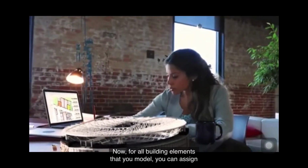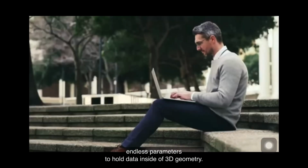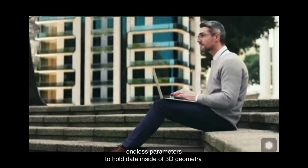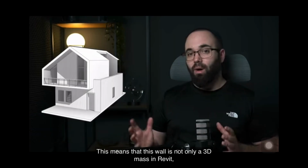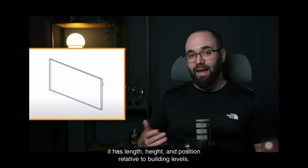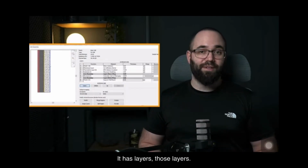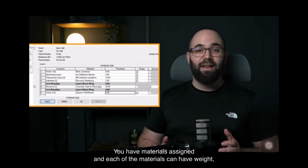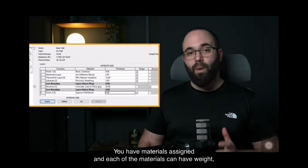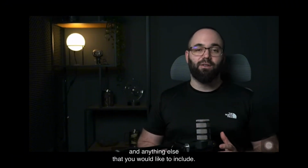Now, for all building elements that you model, you can assign endless parameters to hold data inside of 3D geometry. This means that this wall is not only a 3D mass. In Revit, it has length, height, and position relative to building levels. It has layers. Those layers have materials assigned, and each of the materials can have weight, structural properties, thermal properties, cost, and anything else that you would like to include.